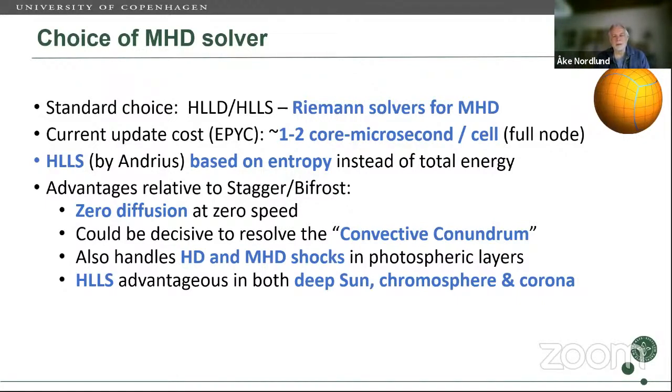Well, there are several good reasons. And you can see them in the red Bible about Riemann solvers, where Toro has some figures showing the difference between HLLC and HLL. The difference being that the HLLC variant of the Riemann solver can represent a jump in density with no jump in pressure, a so-called contact discontinuity, exactly, without any diffusion.